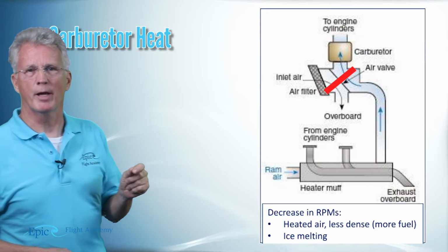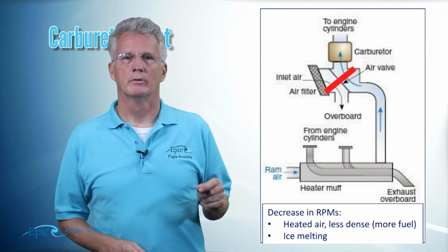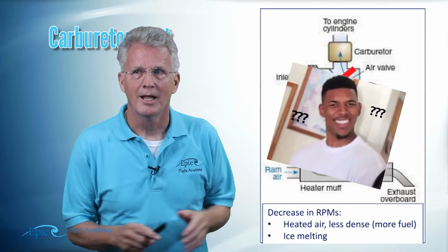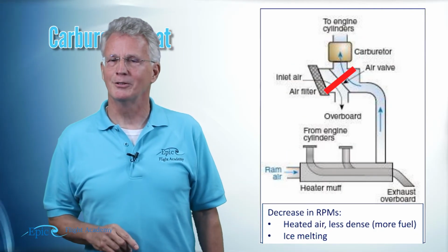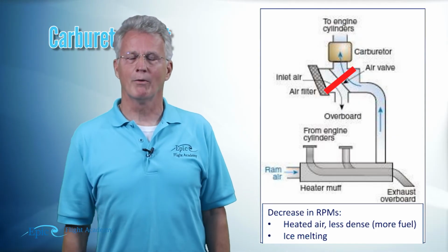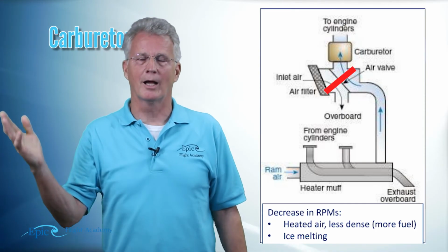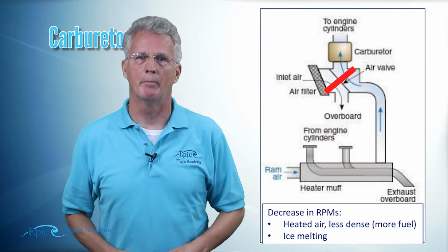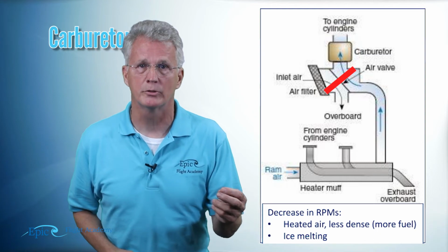If you suspect carburetor ice, wait a minute, how will I know if I have carburetor ice? If your engine is starting to lose power, if it's starting to choke off, you're going to notice some power reduction. You're going to think immediately, aha, that could be ice. I'm going to pull that carburetor heat knob to the on position.